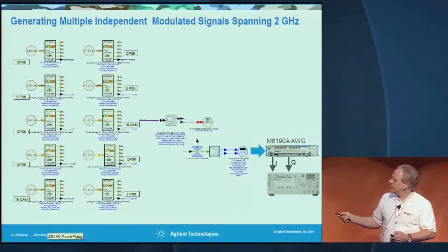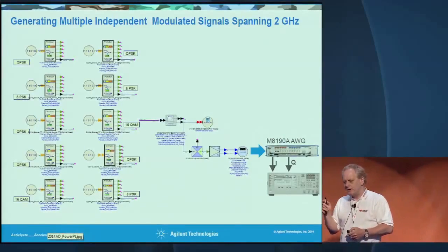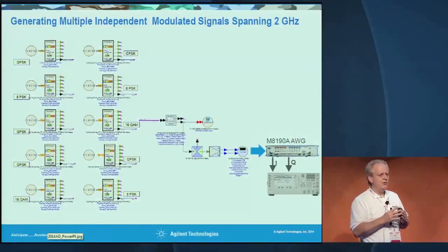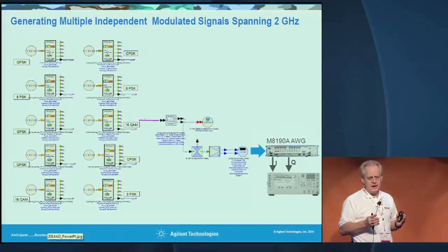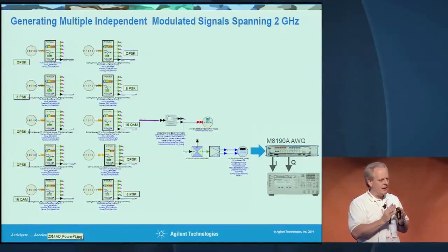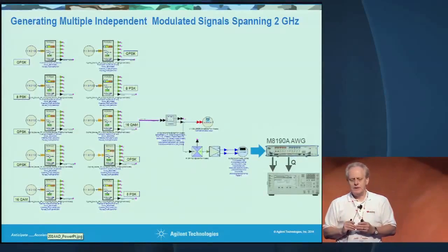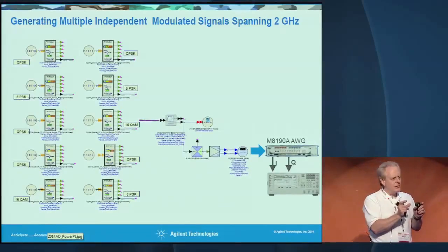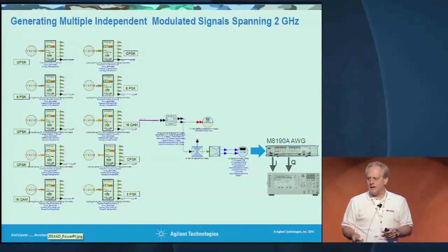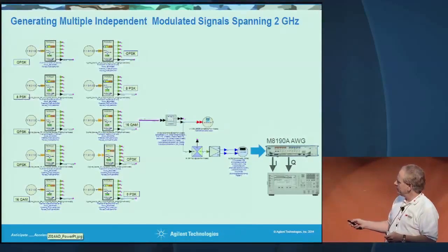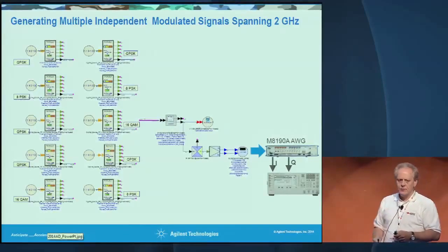Here's a case where I spoke earlier of, in the newer generation of satellites, you can reconfigure the bandwidth dynamically to reallocate for certain service levels to different people. Now, to do that, you're often looking at creating multiple concurrent signals side by side, and to do that, it's possible to set up multi-emitter situations and combine them with a resampler.